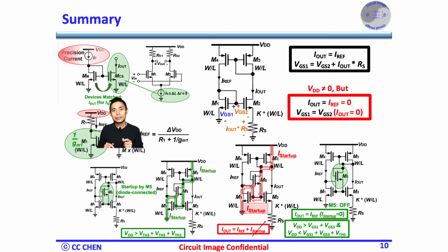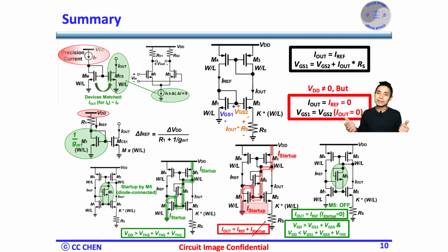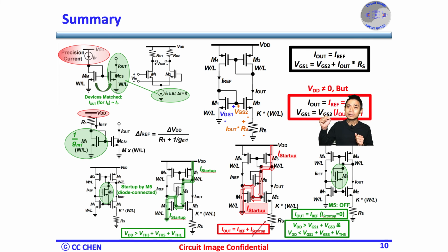To tolerate a higher supply noise without breaking the quality of the reference current, a supply-independent biasing is a must. However, there is a dead zone in the steady state where both IREF and IR current would stay zero even though the supply is powered on.